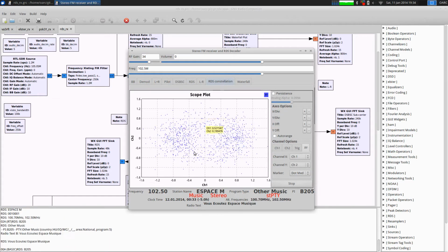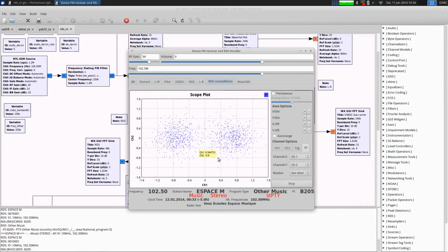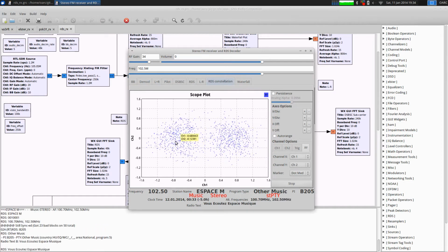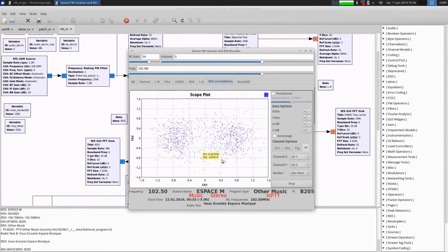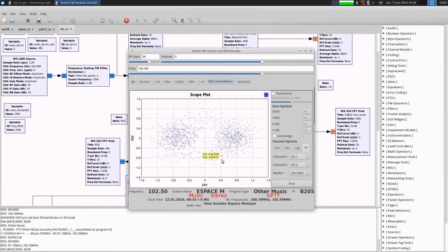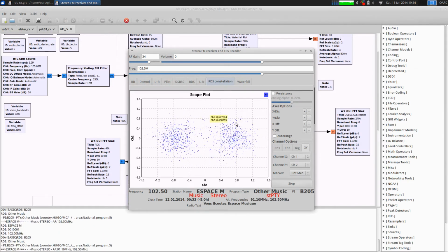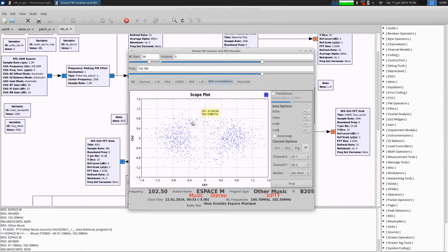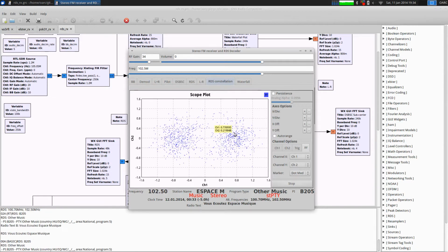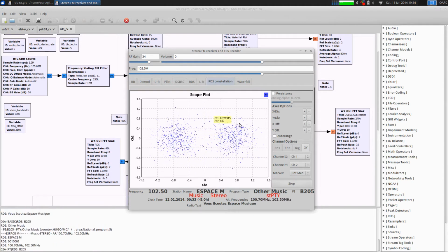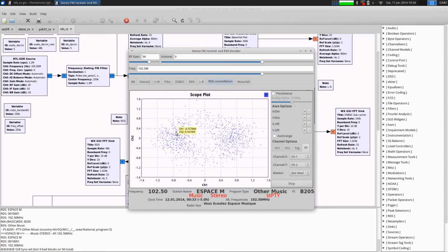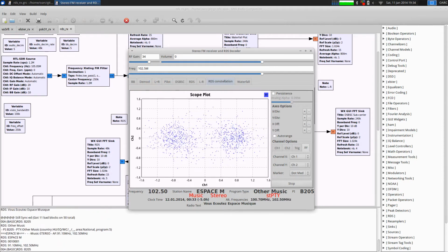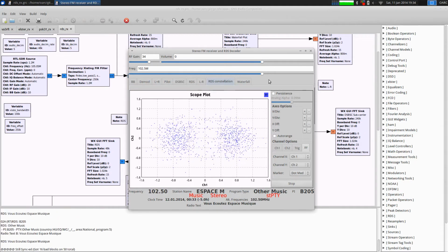This is showing the RDS signal as a quadrature signal, and since it's using binary PSK, just like PSK31, you can actually see there's two different phases, one phase here and one phase 180 degrees away from that, and those are the two phases that are used to transmit 1 and 0 bits in the signal before they get decoded by the decoder.